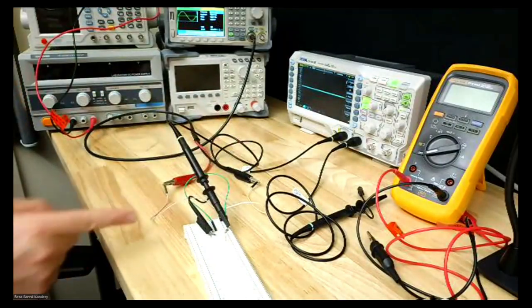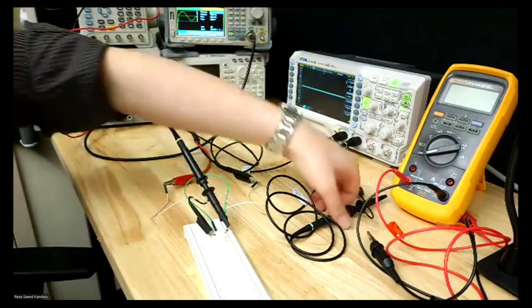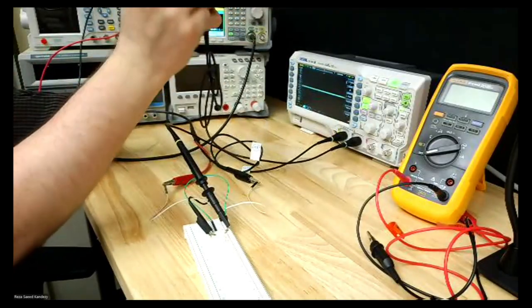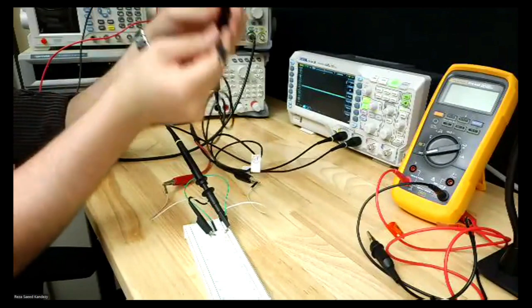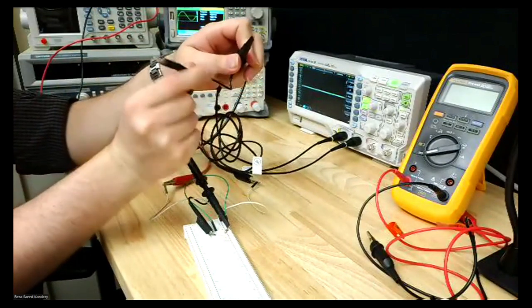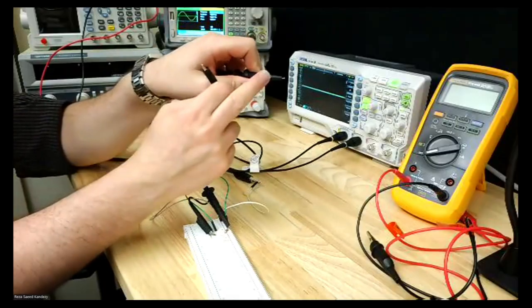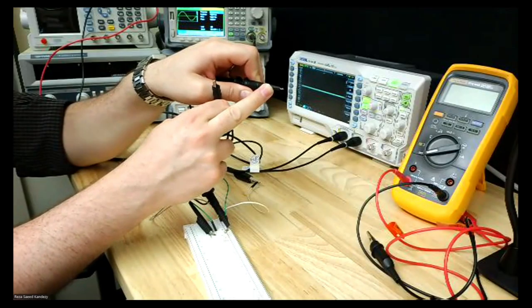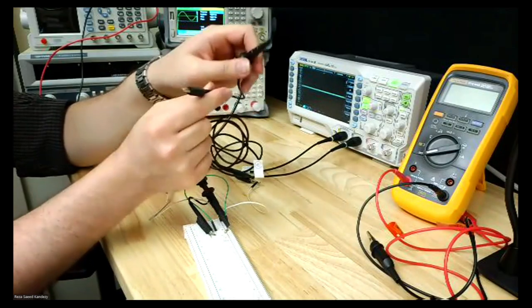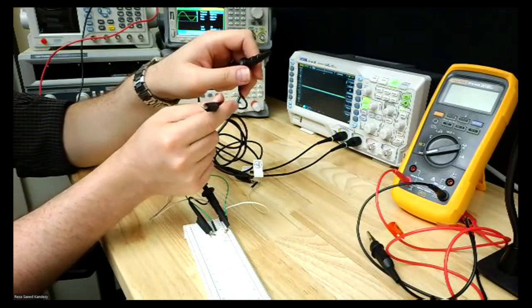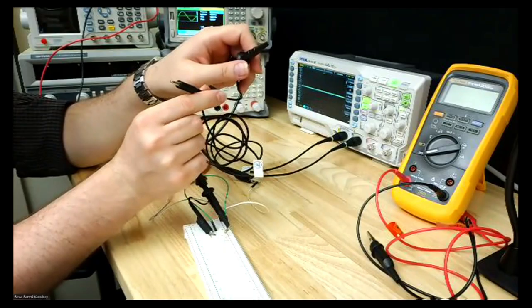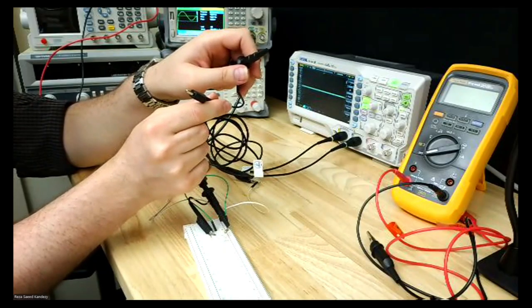Okay, and remember that there are two ports on the probe. This one is the common port. This one is the measurement probe. This one is the common port, and this one is the measurement. This goes to the voltage you want to measure, or current, the signal you want to measure. This one goes to the next terminal across that, normally at the lower potential.